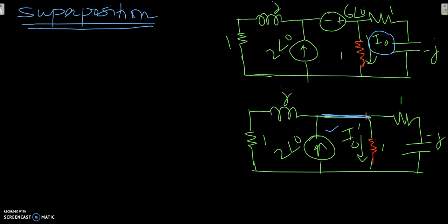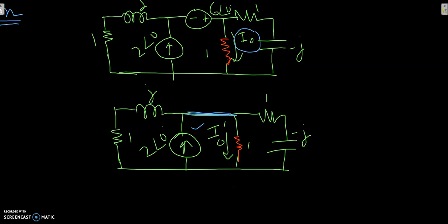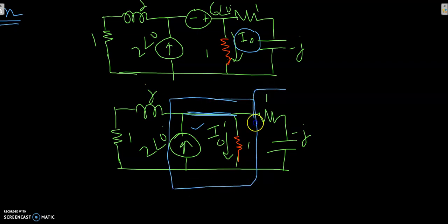So let's start. So basically, the first thing would be to replace the voltage source by a short circuit, which I have done here. So this is my circuit now, and now let me keep this thing intact and replace the equivalent of this. Since these are in parallel, I can rewrite or redraw this circuit like this.